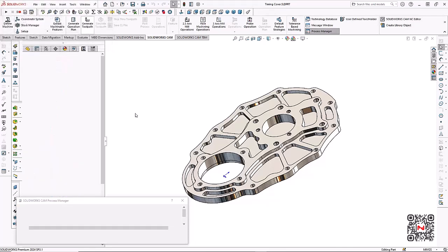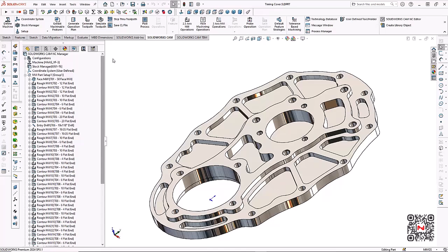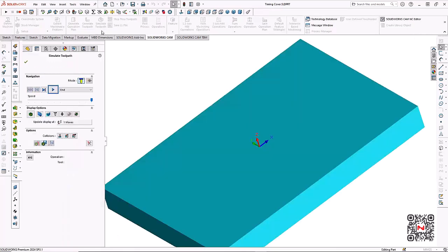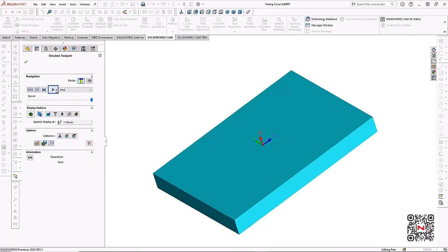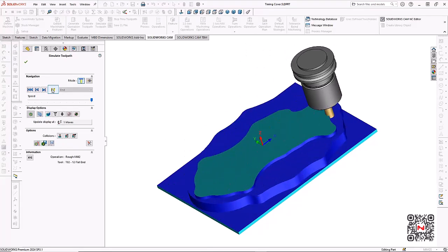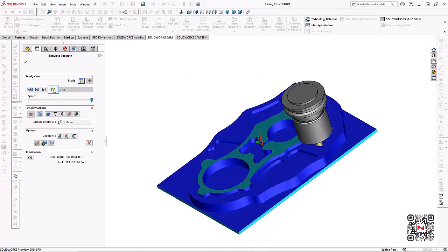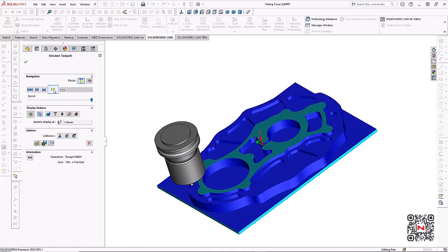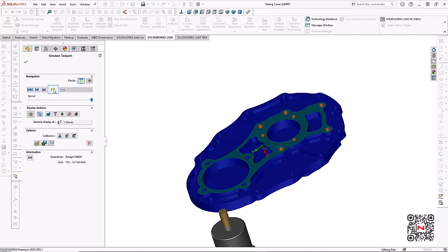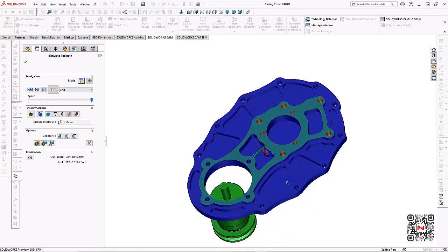I'm creating the toolpaths now for machining here. So it's created all those toolpaths for us now. If I go ahead and simulate, we can now see the machining of the part. I might also mention that I had a piece of stock predefined as a bounding box with a couple millimeters on either side of the part, and 5 millimeters underneath the part to hold the part in a vise for machining.